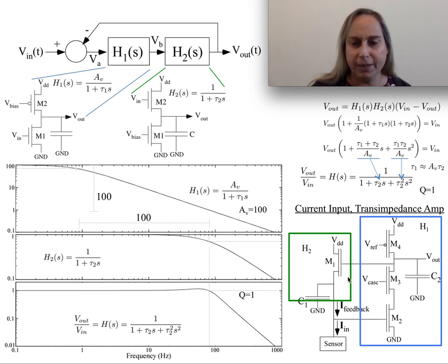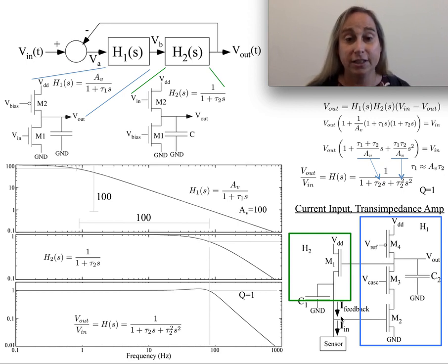But you'll see this show up again and again where I have maybe some sort of sensor, say some sort of typical currents. And I take this, and maybe this circuit on its own is pretty good, but I'm going to use an amplifier in the feedback to do something, say, like fix this voltage node and maybe decrease the capacitance loading of that sensor or something equivalent. Well, in so doing, I've got this entire stability question now that I've just addressed. And I have to think about that and how those things interplay.